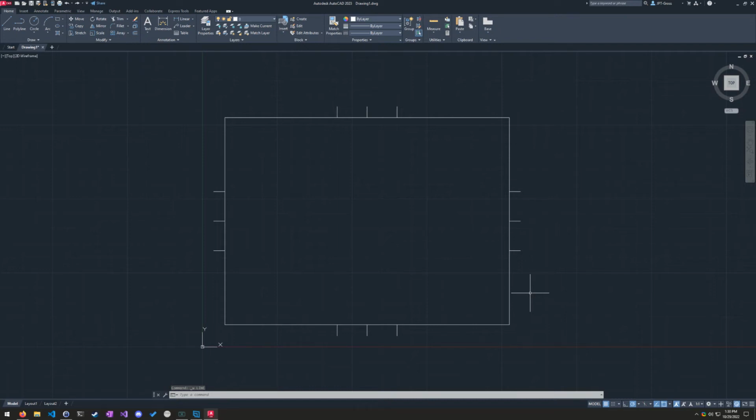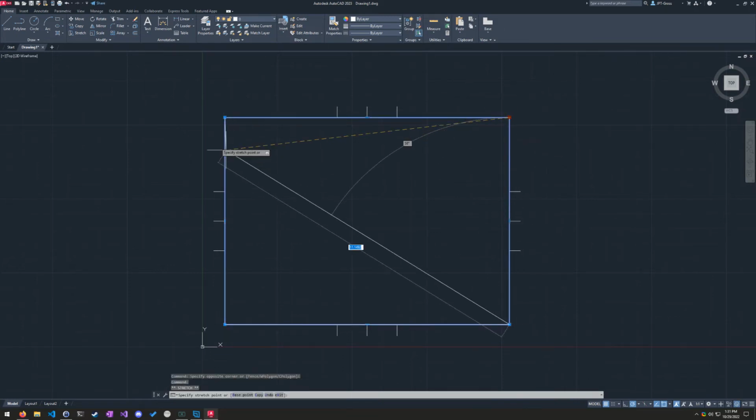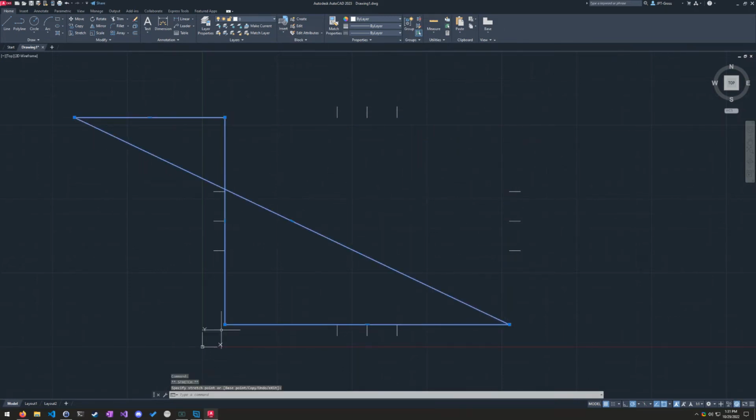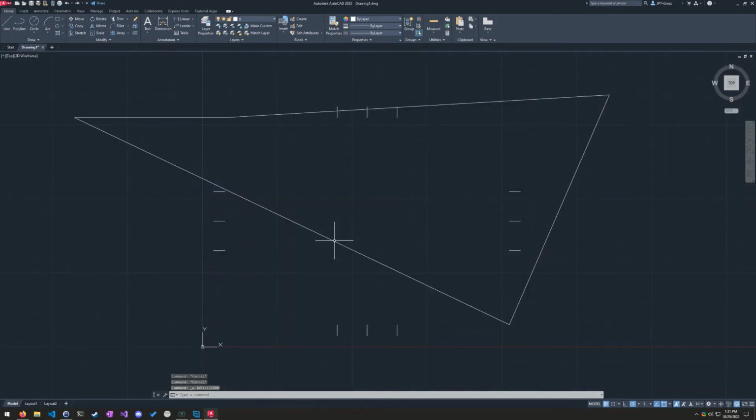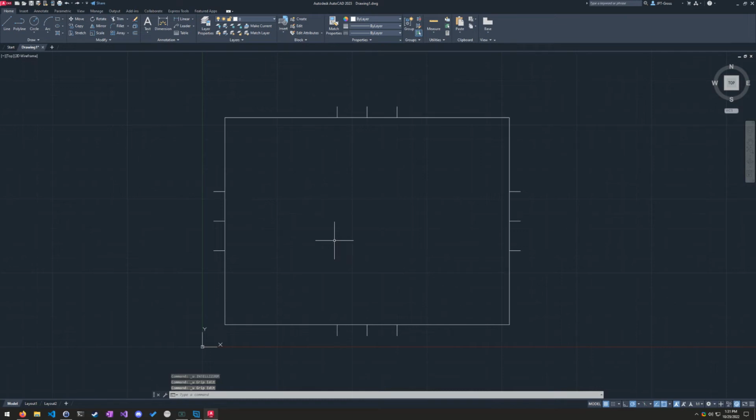And you can just undo until you're back to a position where things look right. I've seen people select something and click and mess all kinds of stuff up. Don't worry. You can always get yourself out of a situation. Just press escape 3 times, hold control, and press Z. And I'm going to do that until everything looks normal again. And then we can continue from there.